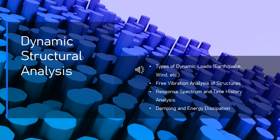Base motion. The ground motion at the foundation or base of the structure can lead to large displacements, which are then transferred to the structure. Pulsating forces. Earthquakes produce forces that can act in all directions: horizontal, vertical, and rotational, but the most significant effects typically come from horizontal ground motion. Resonance risk. If the natural frequency of a structure matches the frequency of seismic waves, it can amplify the structural vibrations, causing potentially devastating effects. Key seismic loads.